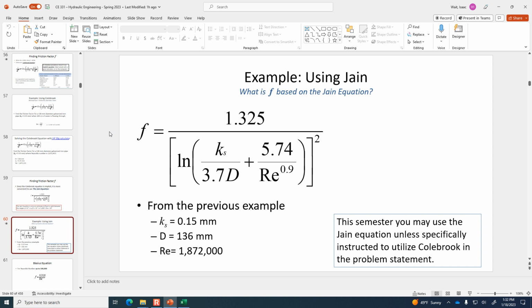Oh yeah, okay, so I guess the actual Reynolds number that we had from the other example was 413, right? I don't know how much, since this was already four digits, that may have an effect. 0.02024. It changes this to 24? Okay. I still got 318. You got 318 by changing that? 413. All right. So the Jain equation, we use it to estimate the f value.